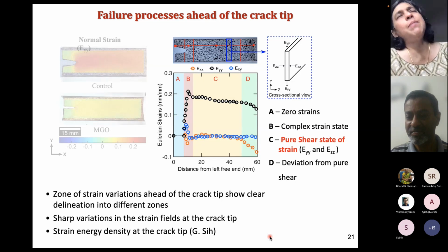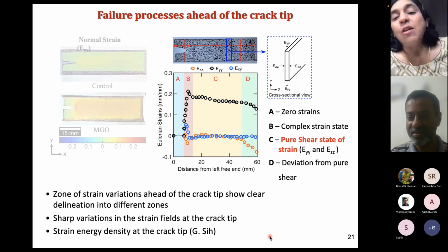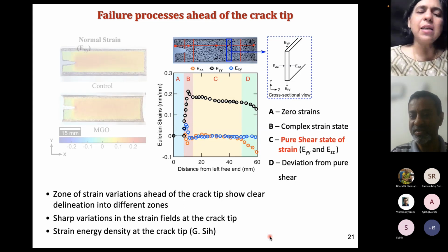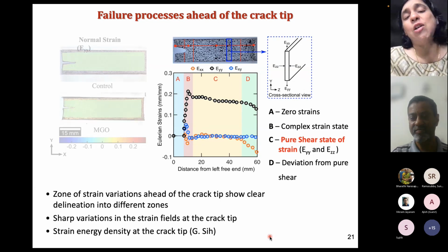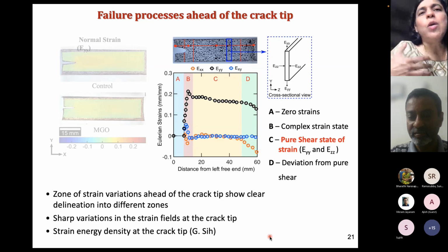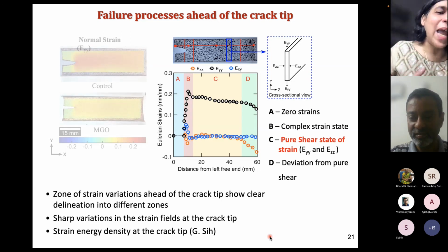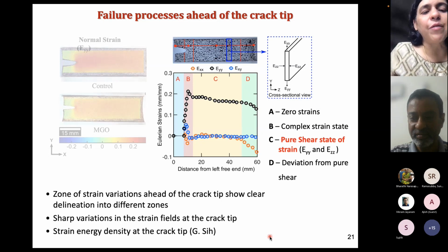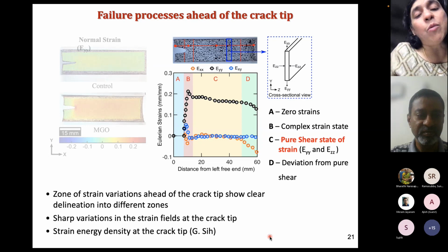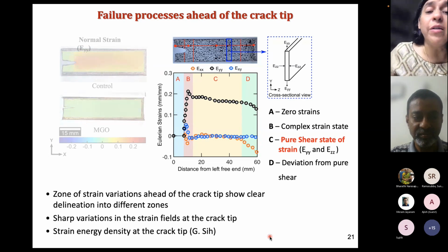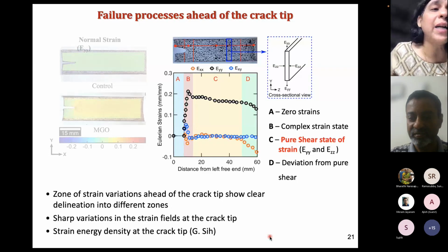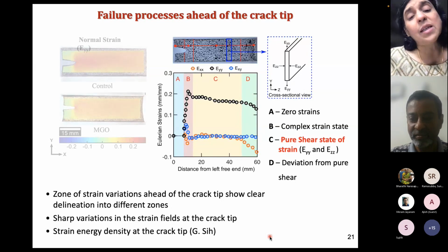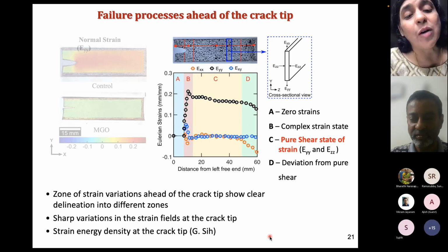So we have thought of blunting purely from the perspective of surface tension related effects. We don't see the surface tension effects contribute too much to metal failures, but we are now thinking that maybe in soft materials you have this surface tension because you have this gel-air interface, which seems to drive or create more and more of those rough edges in really, really soft materials. And that is something where we know that surface tension contributes. So we are looking at various length scales where this could operate, where these elastocapillary effects work. And so we are trying to design our prismatic rods to understand this better.